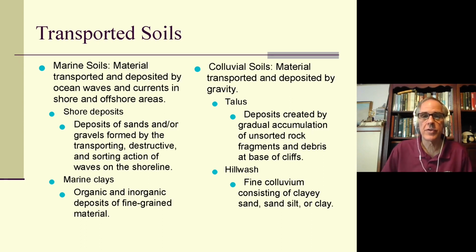There are also colluvial soils, material transported by gravity, which are basically downhill flows of soil, particularly in hills. Unlike alluvial soils, they're not driven by water, they're driven just by gravity, as they decompose and come down. They're generally not the greatest of foundation materials because they're on the move. They've been on the move recently, and they're not well consolidated or compacted.